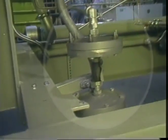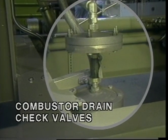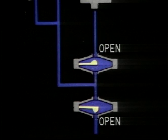The final component in the system is a drain check valve. Liquids that accumulate as byproducts of combustion or residue of fuel gas are drained from the turbine through 2 drain check valves. The normally open reed and half ball valves remain open when the engine is shut down so that liquids can drain.